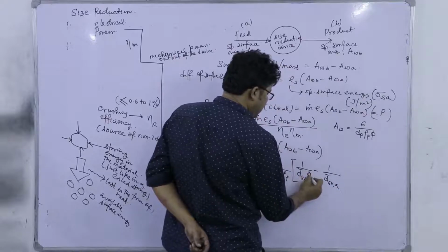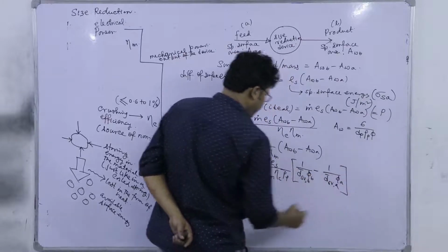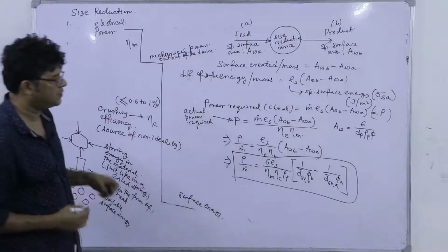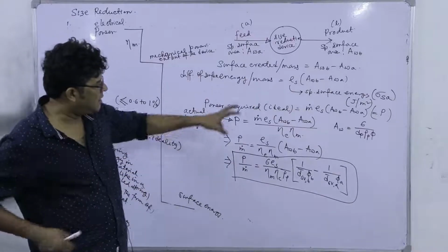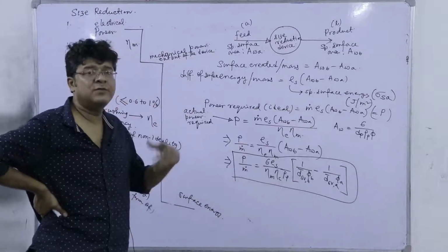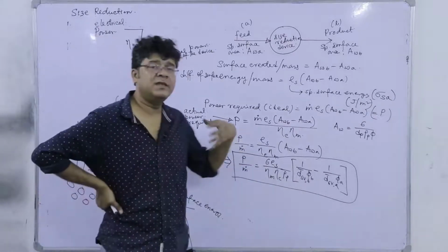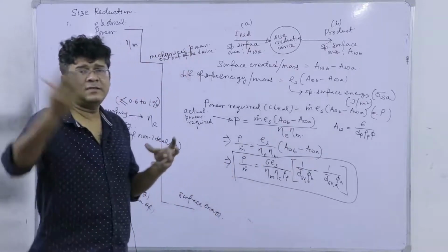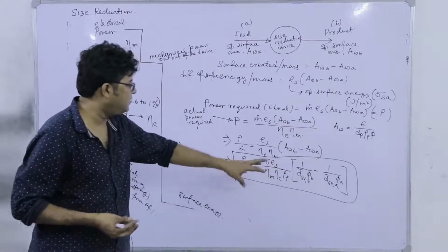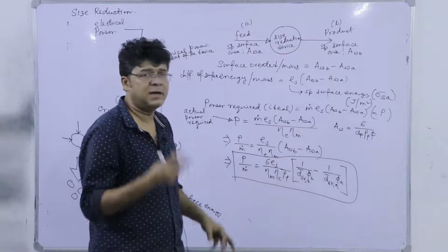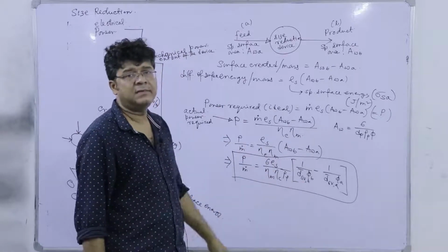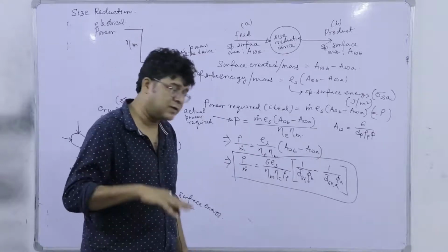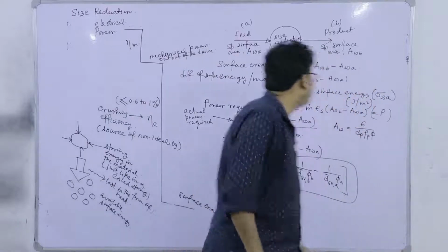We can also think of different sphericities associated with feed and product. So this becomes my actual equation that we can derive from theory. But this will never be a realistic equation because of the term eta C, which you have to determine by experiment. For eta M, again we have to conduct experiment, and eta C varies widely, right. Eta C is 99% lower. Whatever term you calculate, if you divide it by 0.01, it will be 99 times higher than what we have estimated theoretically. So the theoretical calculation actually has no meaning here, though we have to learn it because this is the background.